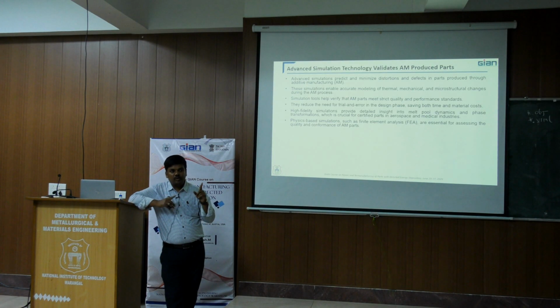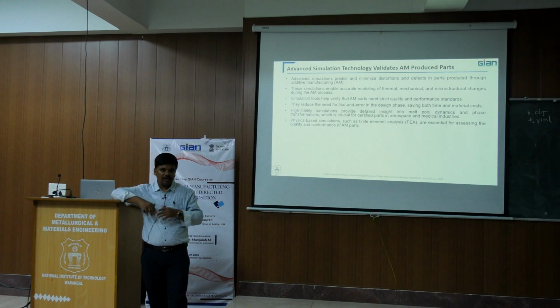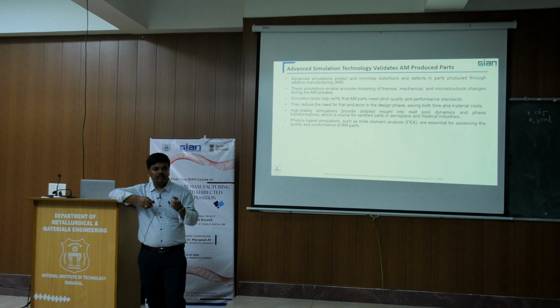The process map is going to give the optimal process conditions where you want high mechanical properties as well as geometrical components with minimal defects. When we develop that process map, we need to understand a lot of application of machine learning. But how is this machine learning feedback signal going to be given to the systems to adjust your laser power as well as the scan speeds?